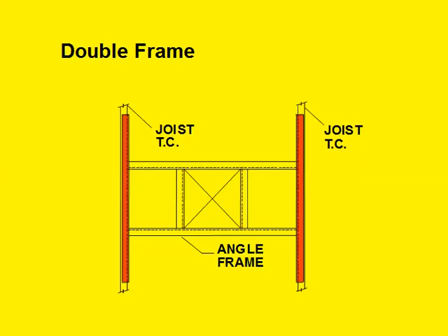And now what I do is I take an angle and make the distance from this point to that point maybe 30 inches. And I design that angle so that it can span 30 inches. So if the joist top chord panel point is here, this has enough guts to span over to the panel point. I don't have to worry about where they are then. I can just set it down and it always works. So I kind of like that, and I think it probably doesn't cost much more than the other type. So you might give that some thought.